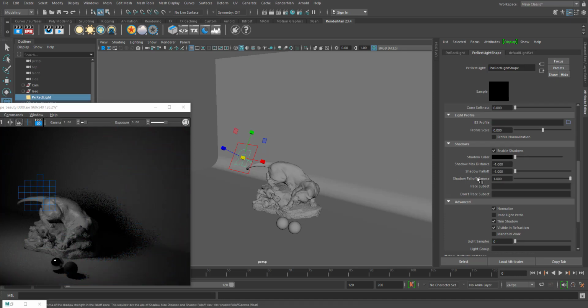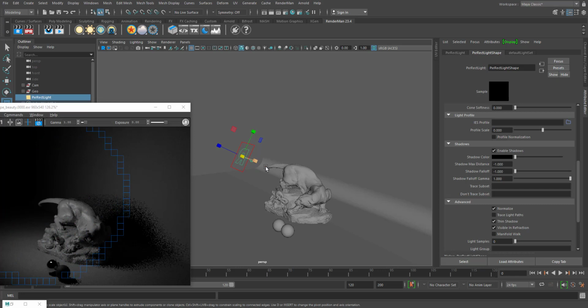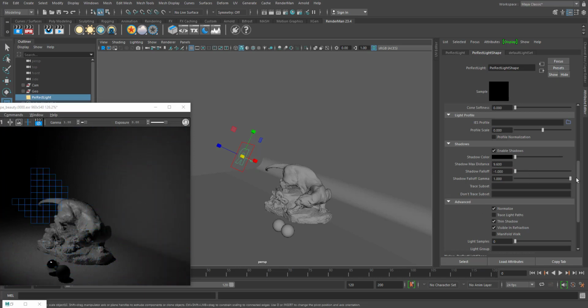the shadow max distance. So let's say you don't want the shadow of this object to be on top of this background, you can use the shadow max distance. Initially by default it will be -1. If it is -1, it is actually infinite, so it uses the full shadow range. When you set this value to a particular number, you can see we are actually controlling the distance through these values. So now if I change the value, the shadow distance is also changing.